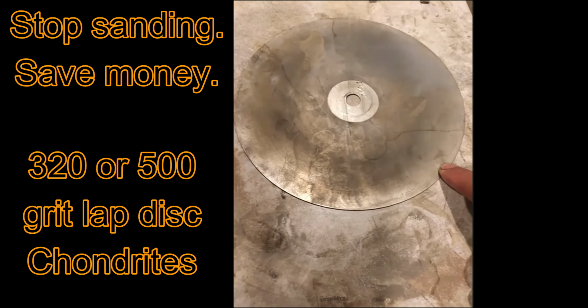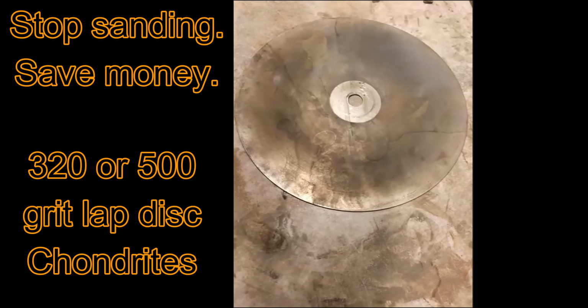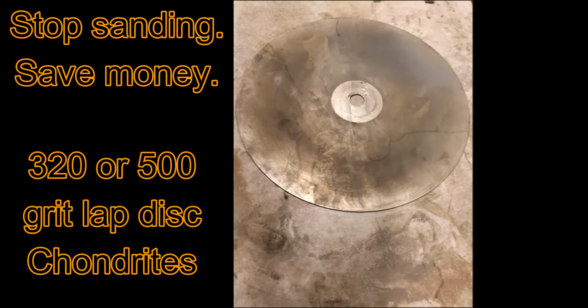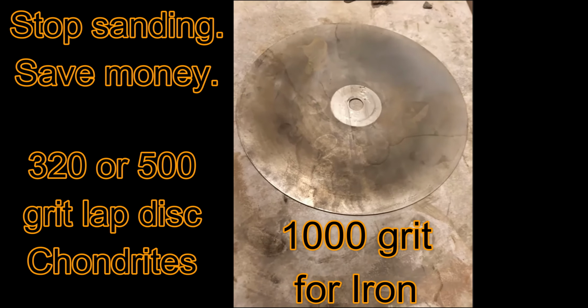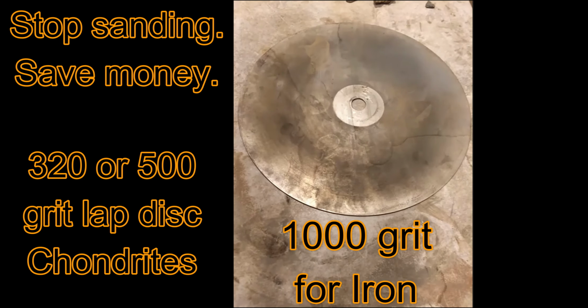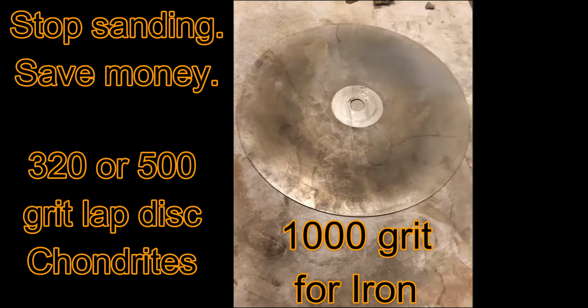And then if you want to clean up slices with just minor blooms of rust around some of the iron blebs, or you have some fine saw marks on there, 1,000 is a decent grit to take things to where they're semi-gloss finish, and they're nice and smooth. So those two are probably the workhorses that I would say to go for. And again, they're like $15. So that is $30. Great. $30 is two packs of sandpaper.